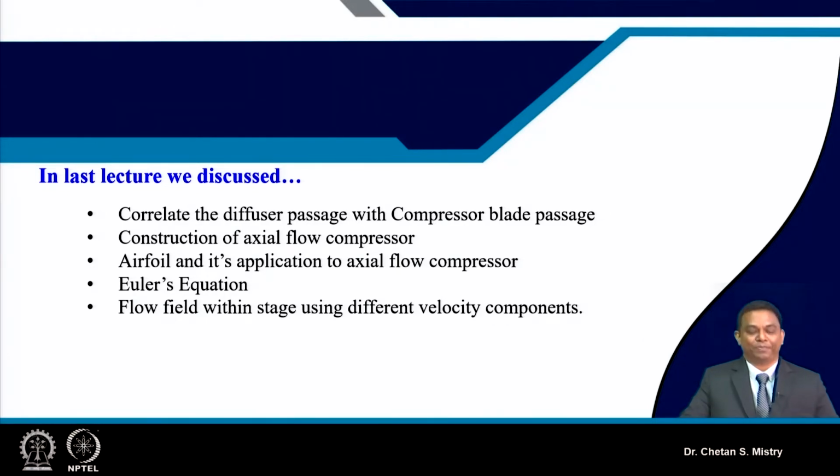Then we were discussing the concept of the aerofoil, which is applicable to our axial flow compressor. Many times people ask what is the use of an aerofoil, and now you must realize that because of the lift force produced by the streamlined body called an aerofoil, we get the benefit in the sense of compression.